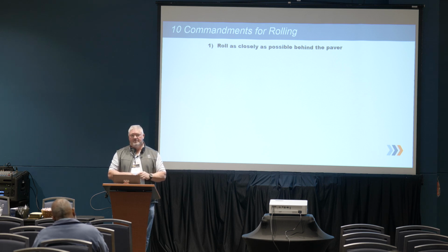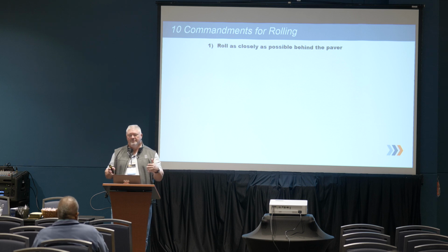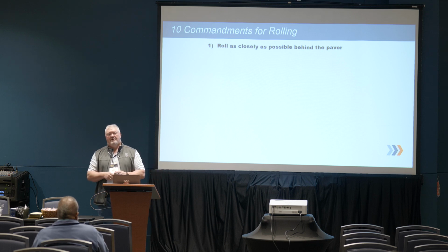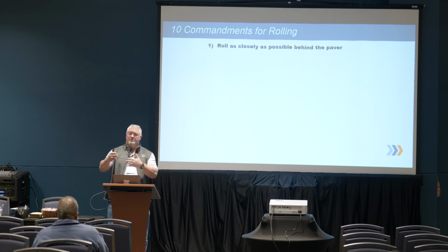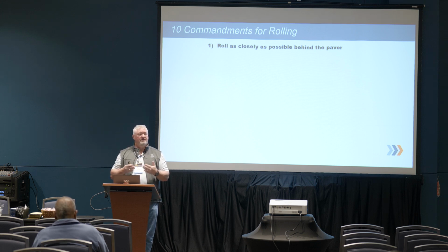So many times I get on a job site, you see the roller guy want to creep up to the back of the paver. I always tell people the closest that roller needs to get to the paver is the length of the roller. I don't want them to slow down, because if you're slowing down to creep up behind the paver as the paver is moving, you're losing time. And you're only running it static anyway. I want you to keep doing your same passes all the time.